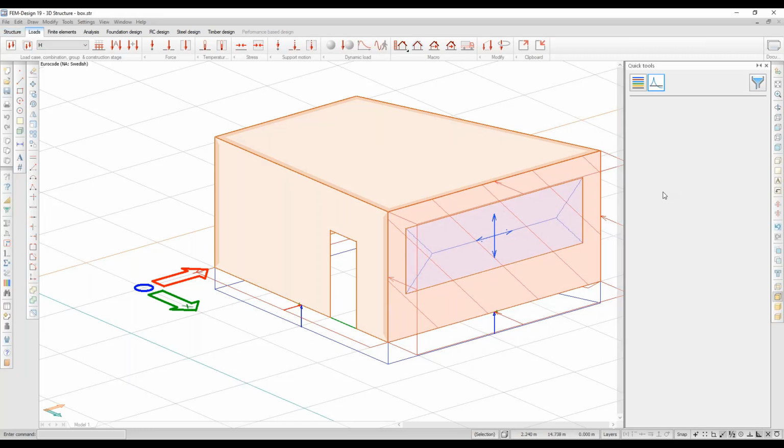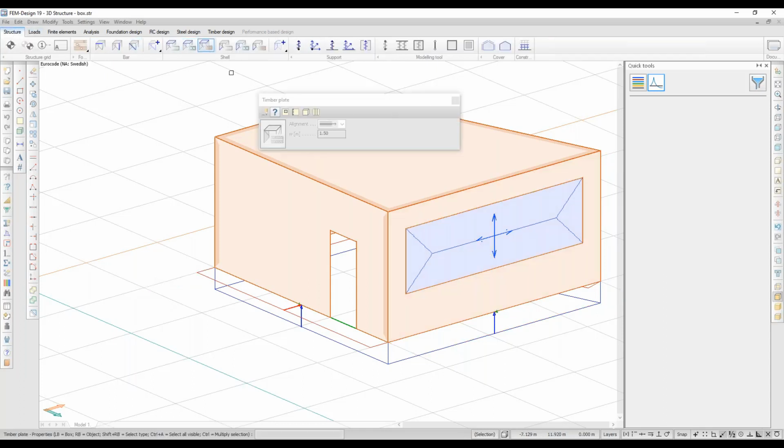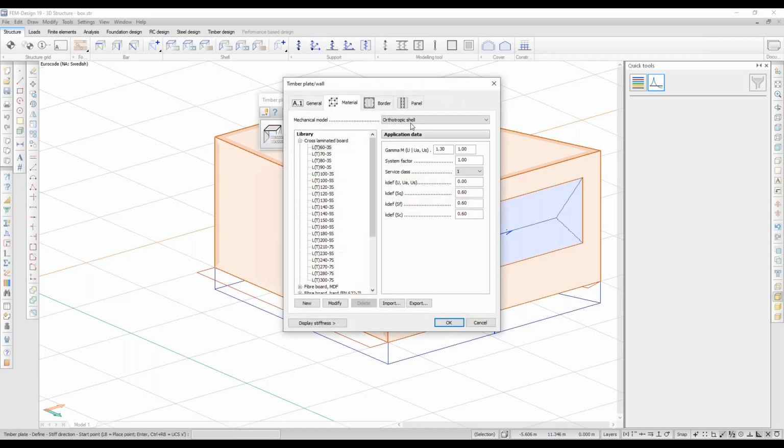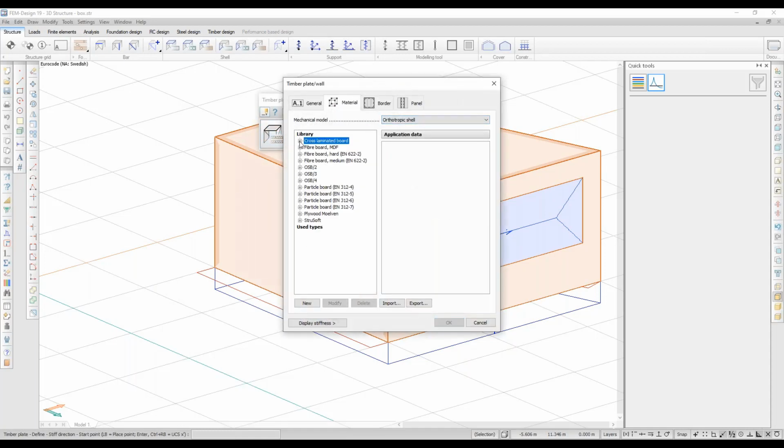There was another question about why we get different material stiffness values by the orthotropic model and the CLT model. The short answer is that it's a quite different mechanical model in the background. An orthotropic shell has a quite different material stiffness matrix compared to the laminated shell mechanical model. The laminated shell model is a much more complicated model with a lot of back calculation and pre-calculation to gain the stiffness matrix.